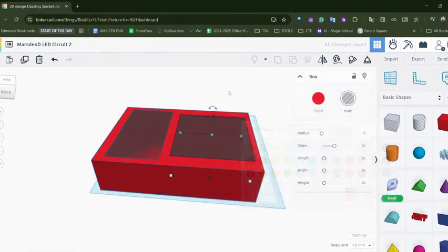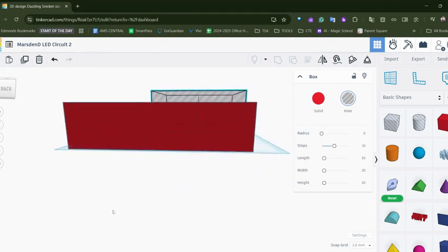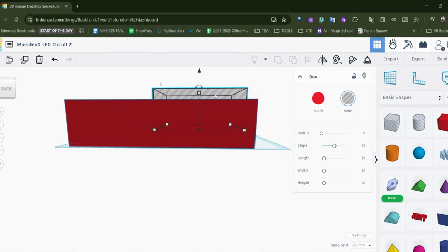Make that solid. Click on this hole. All right, I want to make this a little taller. I want to make this hole a little taller. So I'm going to make it about, let's see if I can make it 5 millimeters taller. I'm going to guess that this can be 18. Okay. I do want it to poke up. I want this one to be a little bit taller too, so it sticks up above, and make sure we cut the hole, but we also keep this down below. So we make a big enough hole that it can rest inside. All right, so this one we want to make taller, and now we want to sink it down, so we can do that. Yep.